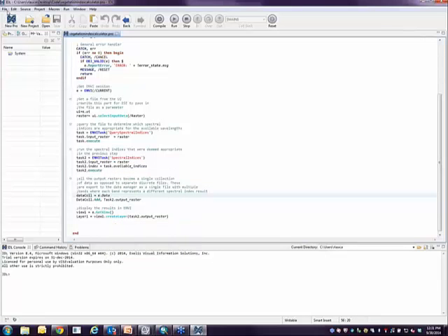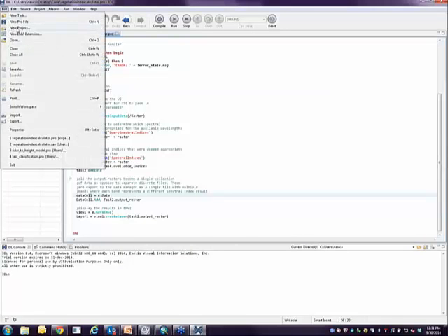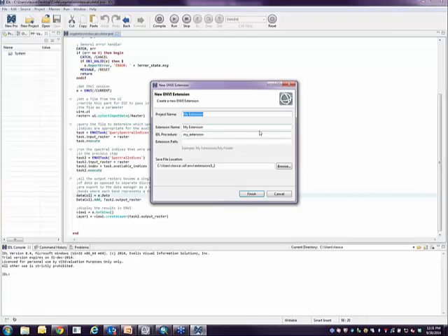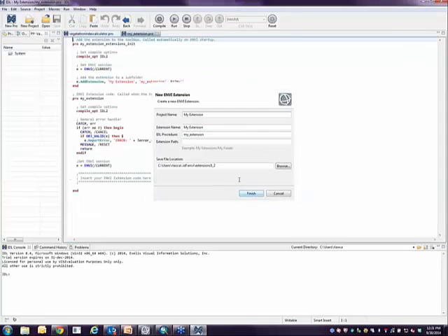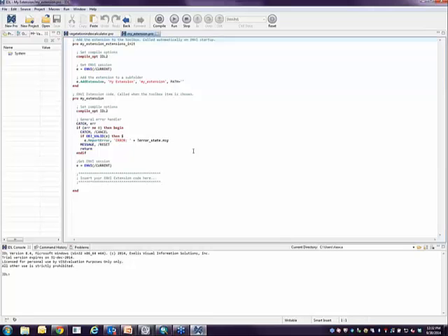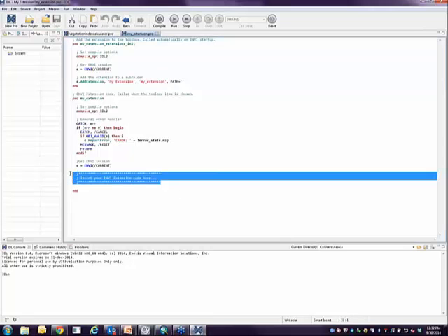The other thing, if you're not familiar with adding a button to ENVI, all you need to do is click this button that says New ENVI Extension. I'm just going to call it My Extension. And you'll see that it creates all of this wrapper code for you, that all you need to do is plug in the call to your tasks right here. And then the next time that you start ENVI, you'll have a new button in your interface that you can use to do something custom. So hopefully we're getting to the point where this is approachable to most everybody to implement in their workflows.